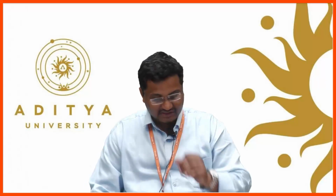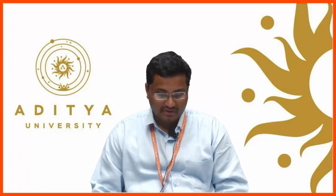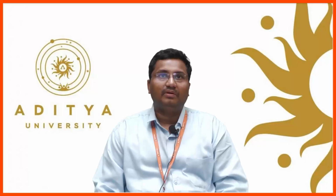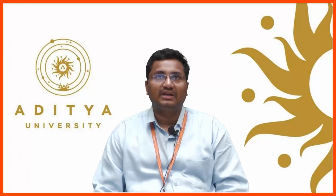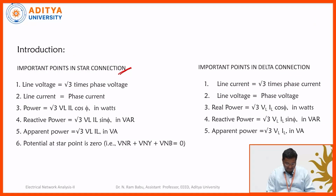In order to start this session, we should be knowing about some important topics from the previous session. First, some of the important points that we discussed in the previous class regarding star connection, followed by delta connection. Coming to the star connection, the line voltage is equal to root 3 times the phase voltage. This equation we have already derived in the previous module. The second one is regarding the currents: line current is equal to phase current.